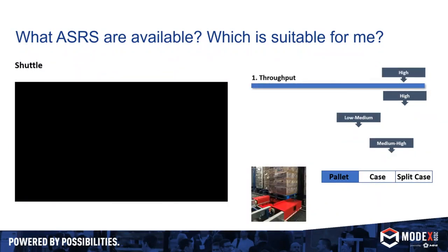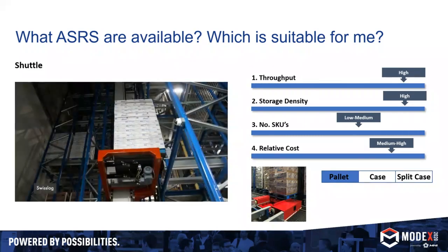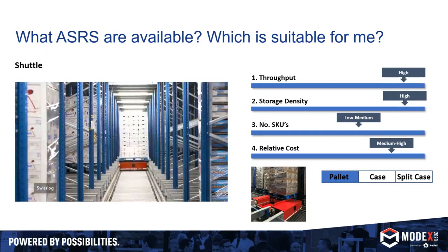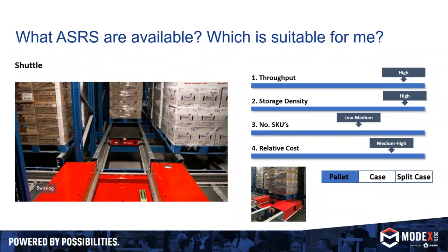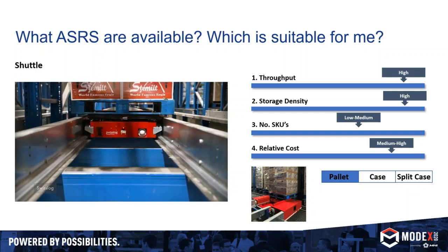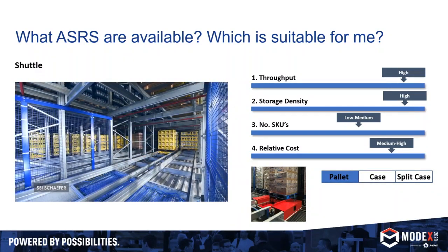Next one in the line, still staying with pallet technologies. This is a Pallet Shuttle. So how does it work? In this case, rather than having a single crane per aisle, we have vehicles on individual levels, each one bringing pallets up and down the aisle. And then on board that aisle carrier is another vehicle called a row carrier, which is then depositing the pallets into the row.